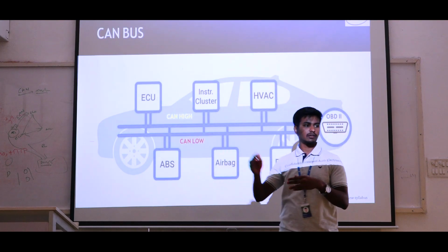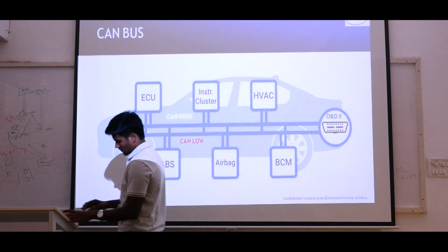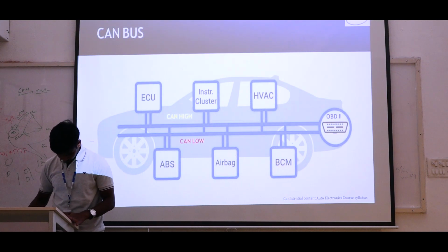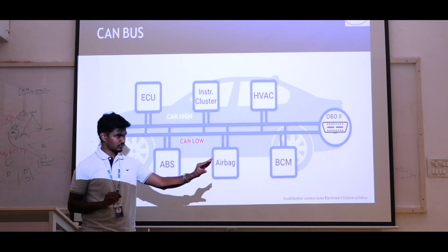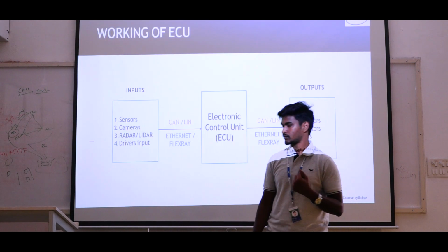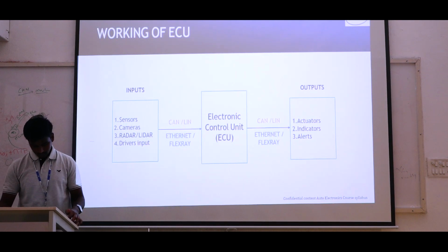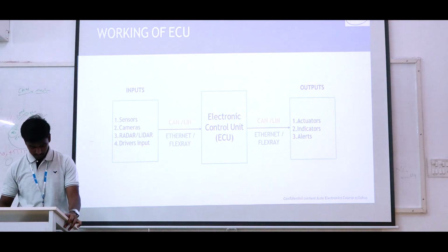Yes, I will explain that about the CAN protocol. It depends on the speed of communication that you want. If you want to transmit data at a fast rate, go with CAN communication. It supports 1 Mbps data. If you want to transmit low speed data, it is LIN, the local interconnect network. If you want to go with the multimedia area, there we have more bandwidth.